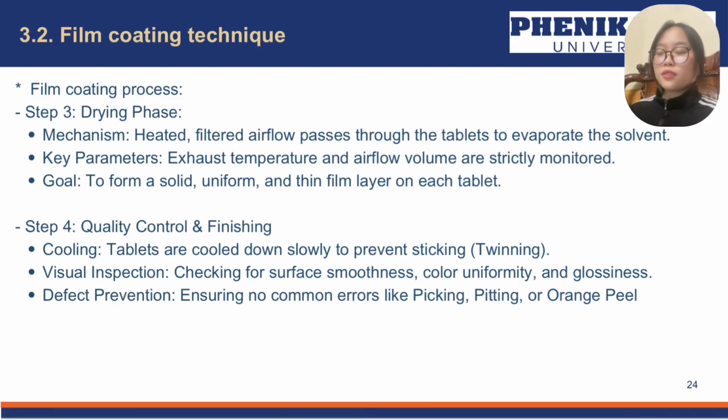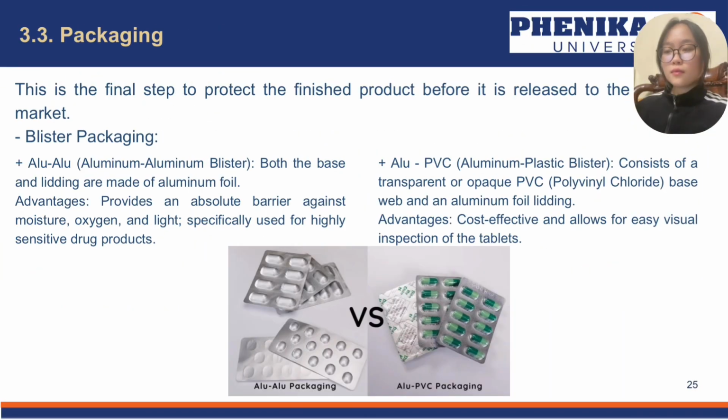And finally, for step 4, it is quality control and finishing. For cooling, tablets are cooled down slowly to prevent sticking. Visual inspection checks for surface smoothness, color uniformity, and glossiness. Defect prevention ensures no common errors like picking, pitting, or orange peel.